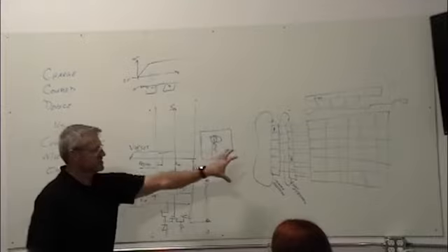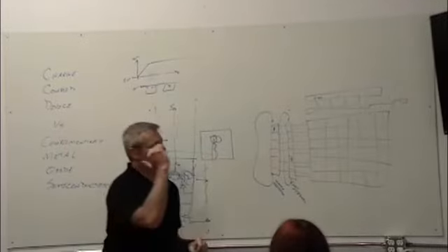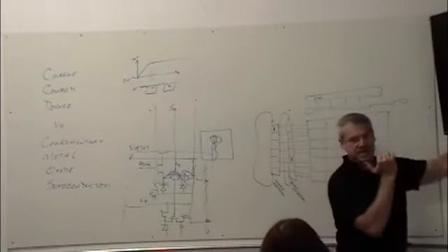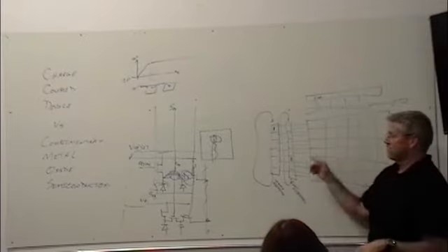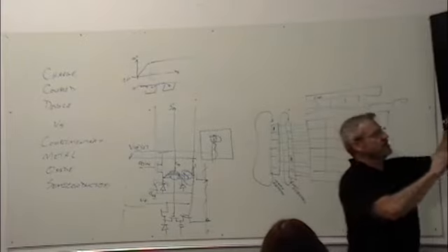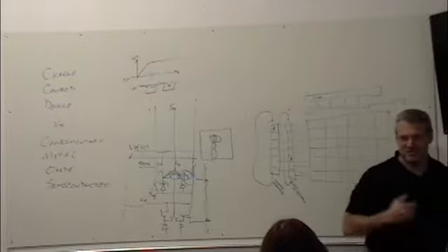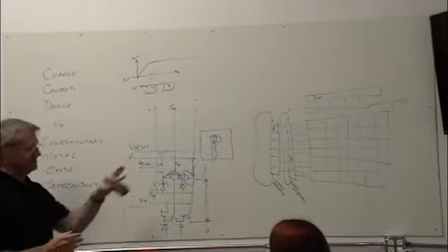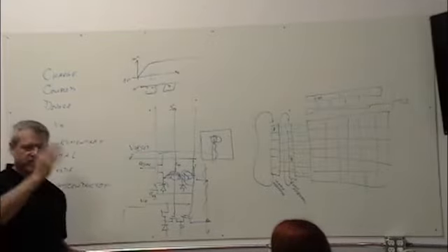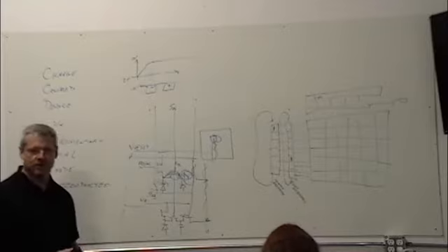If you take a CCD camera and you point it at the TV, you'll see the scan line, right? You can watch the scan line roll because they're not in sync. If you take one of these and point it at the TV, you'll get these funny double bands where it's like all black, but there's an image going through because they're out of sync. You start getting weird, funky effects that this causes in one direction, but not another. Orientations. Well, yeah, and so it becomes a trade space, right? What do you want to do?